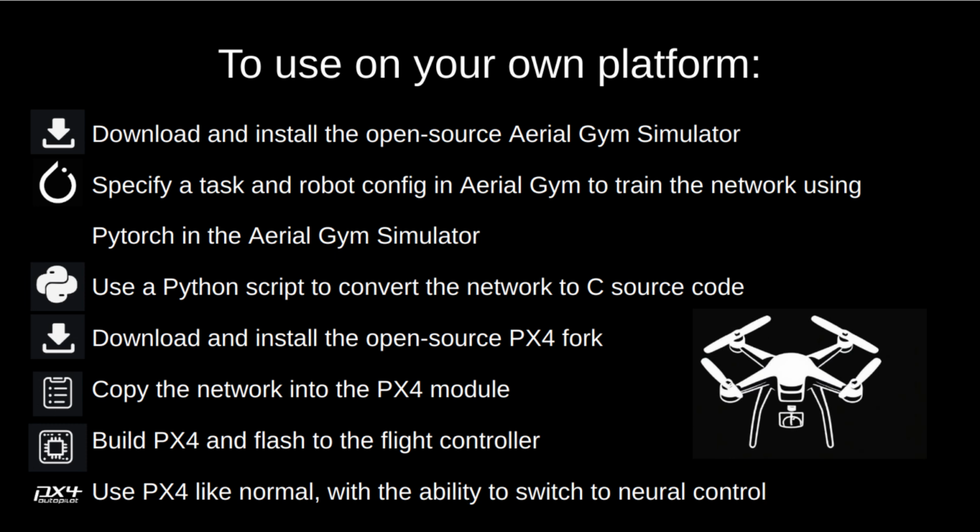First, you can download the Aerial Gym Simulator and configure what policy you want to train in the PyTorch framework. Then, a Python script is used to convert the network to C source code, compatible with embedded flight controllers.